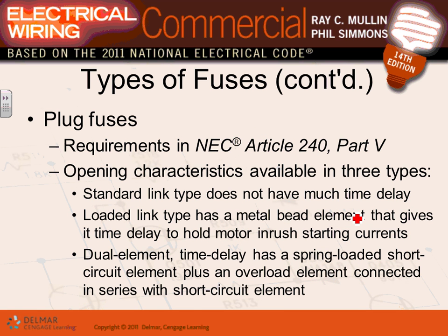This is talking about the plug fuses, guys. You can plug them into a socket. There are a couple of characteristics for them. For example, they have the standard link type, which does not have a time delay. If you want a time delay, this one, the loaded link type, will give you a time delay fuse.